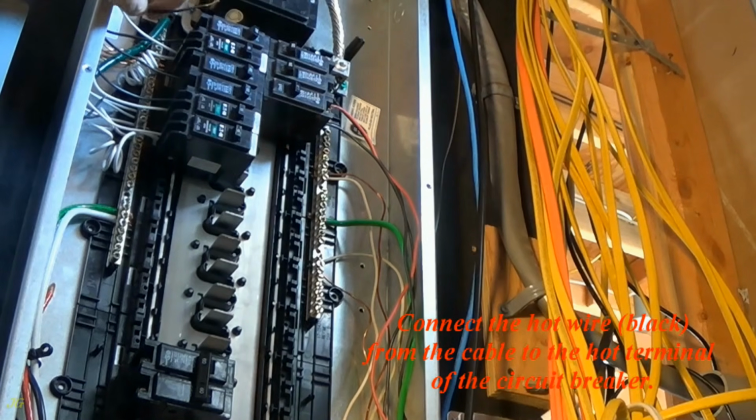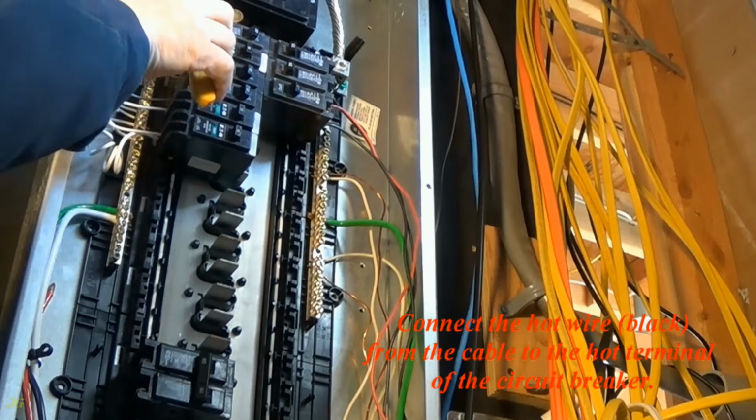Connect the hot wire, black, from the cable to the hot terminal of the circuit breaker.